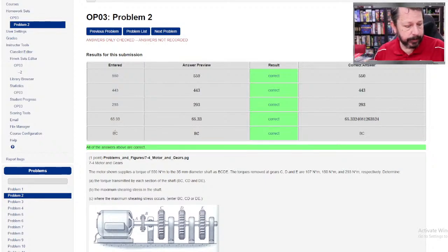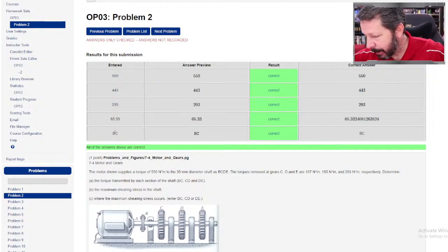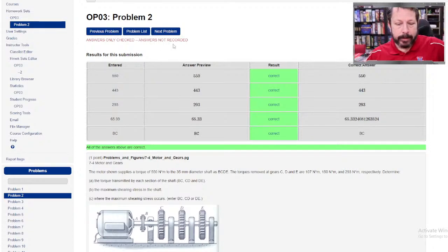So that's kind of the basics of how these problems work. They don't get a whole lot more complicated, but things that could complicate them are maybe the shaft steps down and changes sizes, so you have different diameters or radius numbers. Maybe it's hollow somewhere and solid in another place. Maybe you're trying to solve for the shaft diameter. So there's different ways to approach the problem to make it simpler or more straightforward, or more complex.